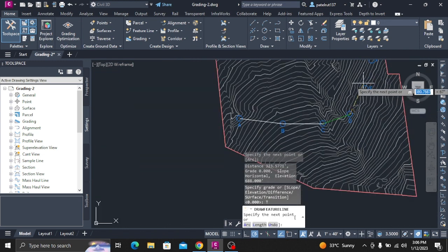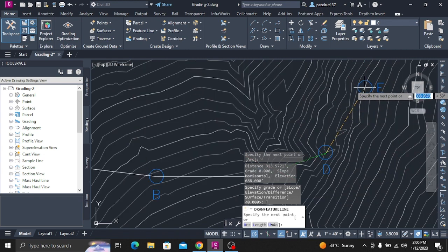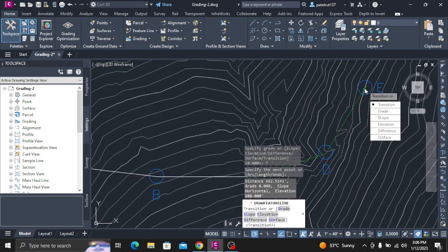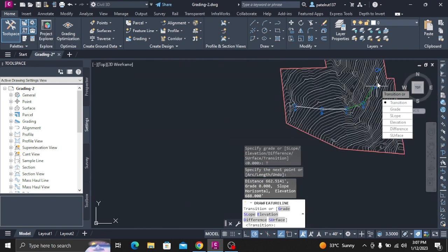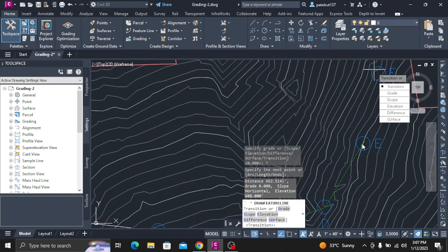Click Feature Line BC again. An elevation point has been added wherever the line crosses the edge of a triangle in the TIN surface. Right-click and click Elevation Editor. Click to close the Grading Elevation Editor.